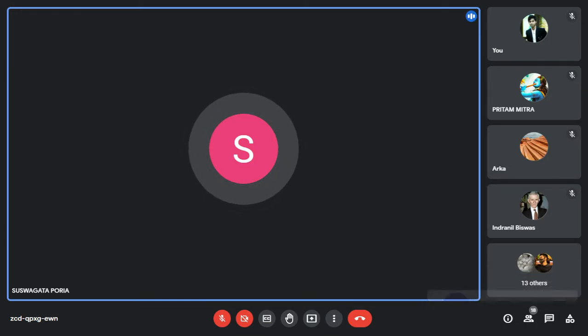And when you want to change something, you have to go to that command, that is MS, model space setting. And when you have to come out of that, the command is PS, paper space setting. Okay, these are the commands. If you use them in the layout, then there will not be a problem. There is no need to set a customized scale. You can put your drawing in the layout by using 1:1 scale also.